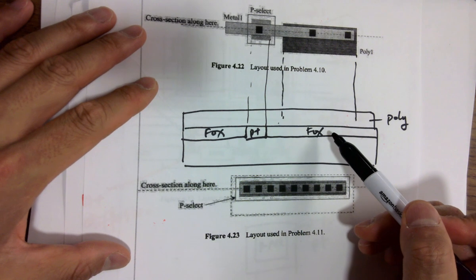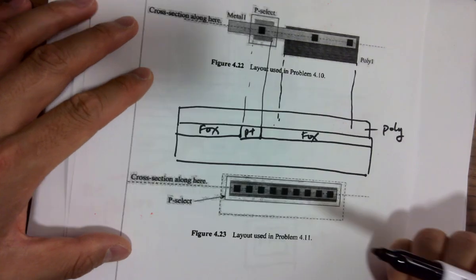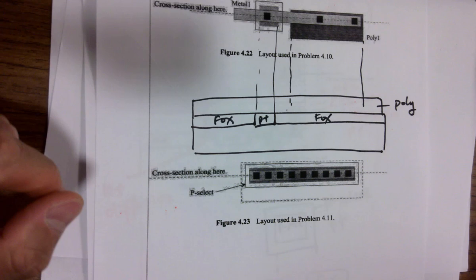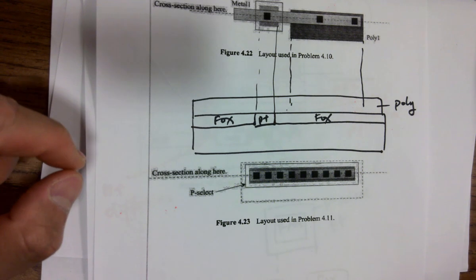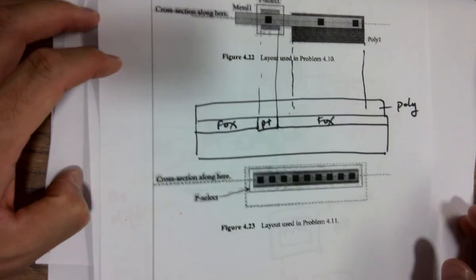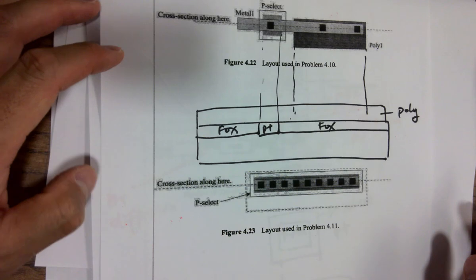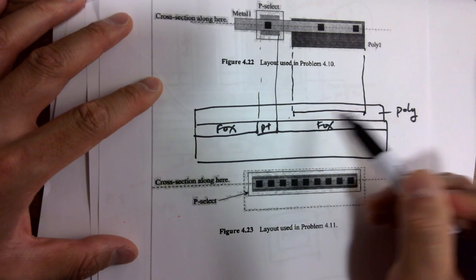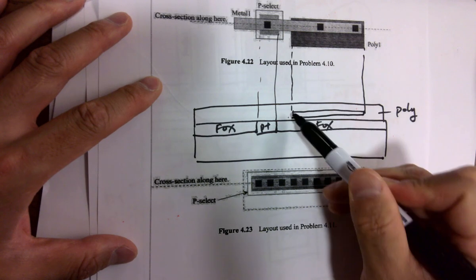That is why there's no direct contact between the gate and the diffusion, because they are trying to generate a little dielectric material in the middle. Even though the gate oxide layer is super thin, there is a gate oxide layer. So we'll draw poly floating in the middle. It's not directly touching the bottom.